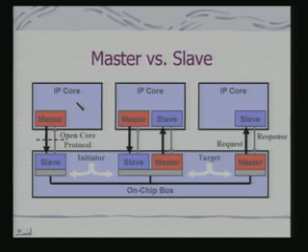So, basic idea, look at this, that I have got this IP core. These are different IP cores. This is basically my on chip bus. And these on chip bus have to be definitely in a hardware implementation in terms of a signal. But these requests that my master and the slaves would make, these requests or the transactions are defined through this open core protocol. So, once these transactions are defined through open core protocol, there is a standardization in the nature of transactions.